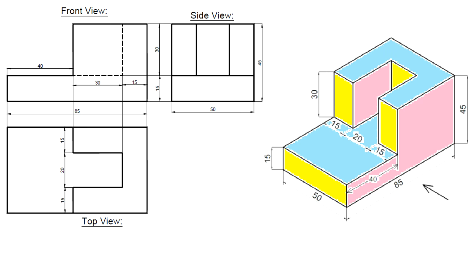So the hidden line, this line will not be visible in the front view. This line is not visible, because it is hidden by this, but this line also will not be visible because it is hidden by this. These two edges will not be visible, but there is nothing to hide here. So that is why we will be indicating this with the dotted line. Then we will go to the top view.